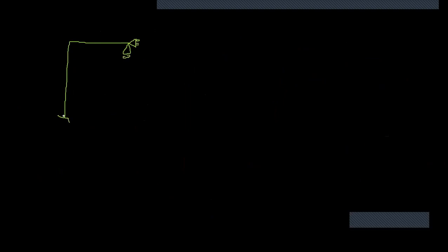Here it's a fixed support. So I know the distribution factor is 0. I have already explained everything in the first step. So here the distribution factor is 1. That means whatever bending moment is applied, this member has to take 100%. Here you have two members, so each will take some amount. That's the distribution factor.